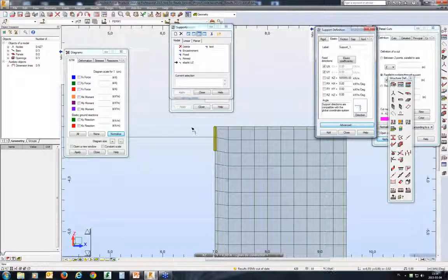Compare with the results without emitters, and shall I always use emitters? Guillaume responded, the emitter function allows you to use the reduction forces option. That can't work correctly if the mesh is not thin enough around the column. If the mesh size is too big around the zone, the reduction force might overestimate the reduction.